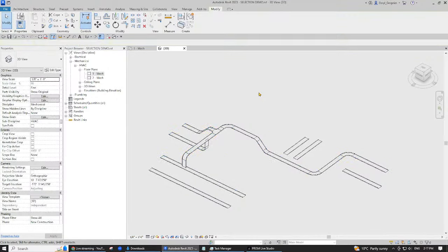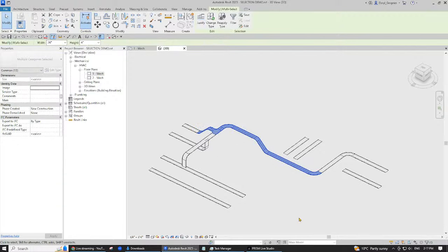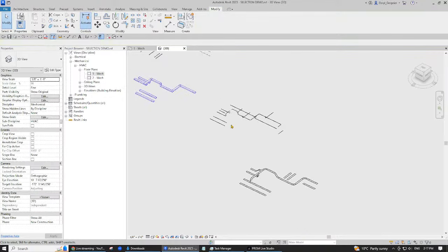You can also do a pinch between two objects. So let's say I want to go from this elbow over to this elbow. So pick the first one, hover here, tab, and then click, and it'll pick between those 2 points. And then you can do what you want with it, right? So let's go over here to our pipes.